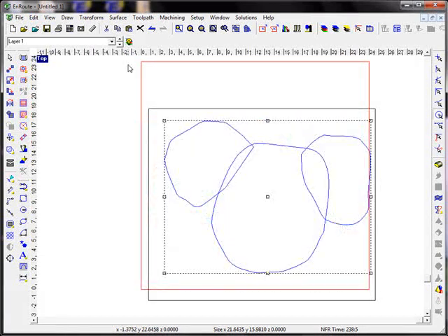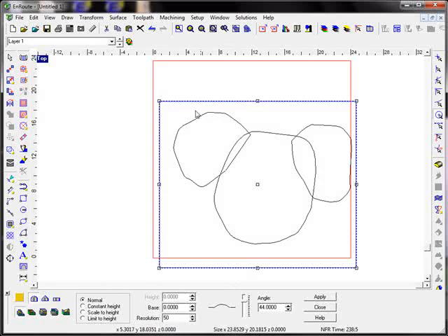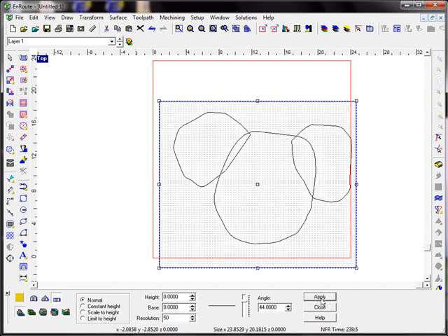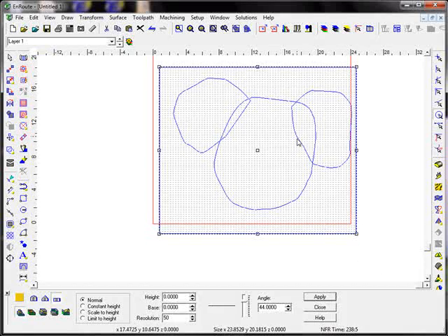So let's come here and make a relief. And this is a fairly big part, so I'm going to leave this at 50 resolution flat and hit apply. Now I'll take my relief and my three objects here, and I'm going to hit add to relief, rounded. I'll come and soften that a little bit and maybe put a small base on there, 0.025, a small vertical base. We'll do a merge highest here.